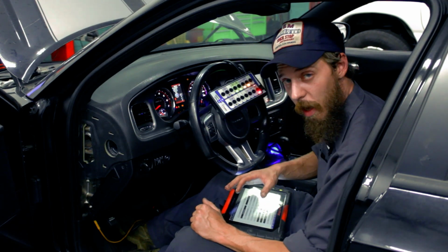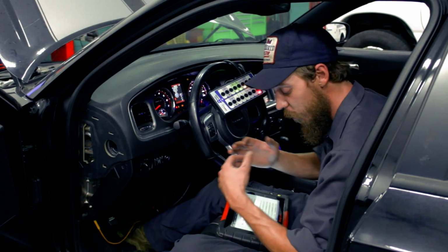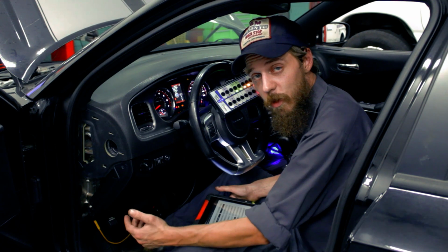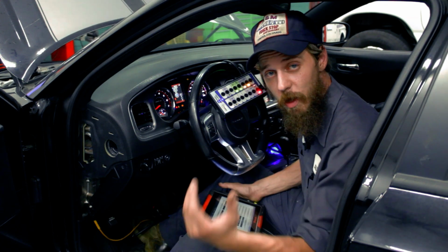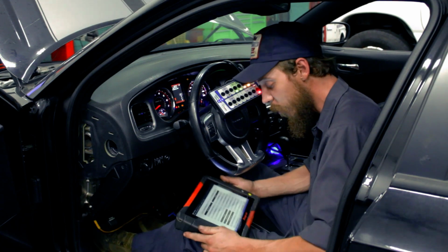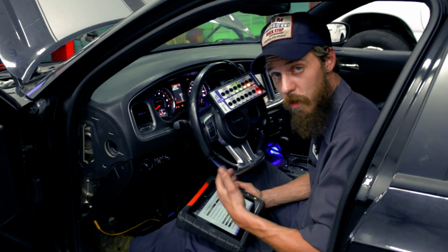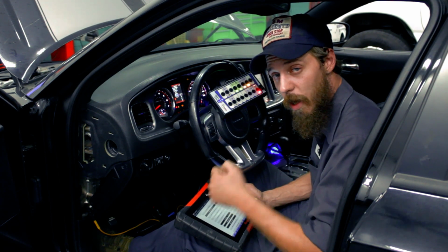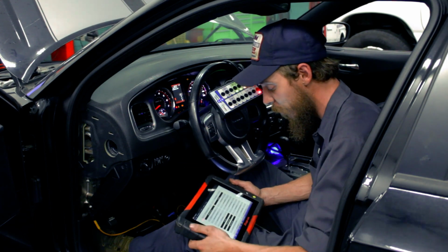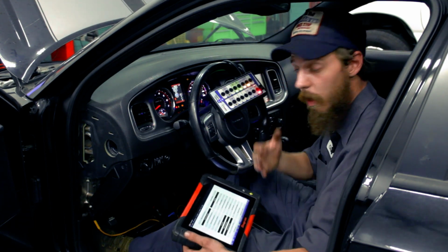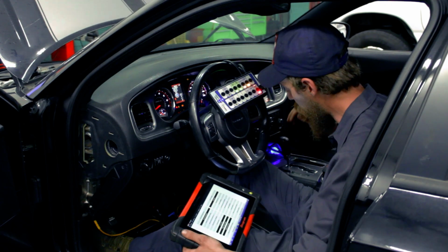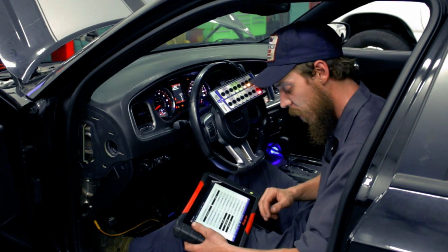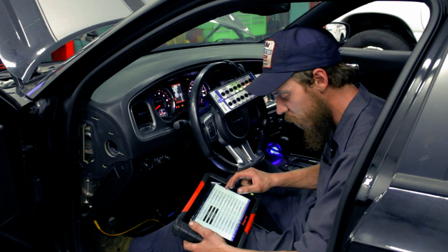So I'm already into the scanner, already into the transmission control module, and I started highlighting data PIDs that I'm concerned with based off our interpretation of service information and what we've seen in other modules so far. We've said it time and time again, brake pedal depressed on a remote keyless ignition system. Very important to see that brake pedal in all the modules that are involved in the starting system. Current gear we want to see. At this point, current gear should be a direct input from the transmission, not a bus or indirect input. We have an OK to crank data PID that we see here.